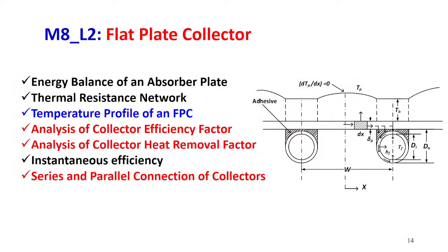And in lecture 2 of module 8, primarily we have discussed the energy balance of an absorber plate, thermal resistance network, then temperature profile of a flat plate collector, then analysis of collector efficiency factor and collector heat removal factor, then instantaneous efficiency, and then finally we understood the series and parallel connection of collectors, and what condition we need to connect the collectors in series and what condition we need to connect them in parallel.